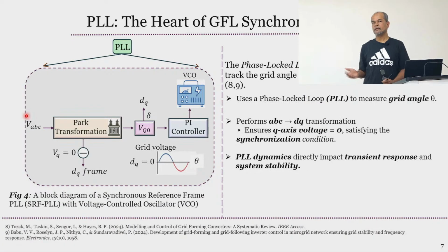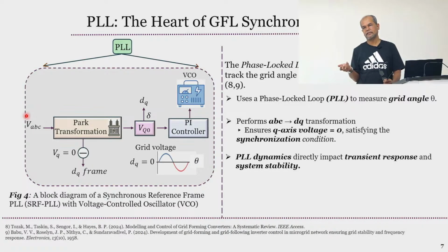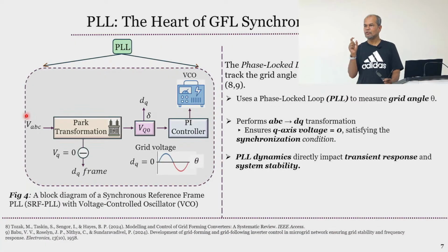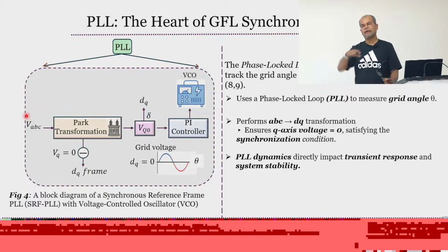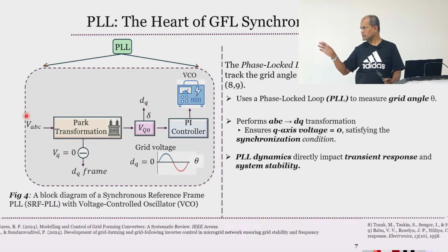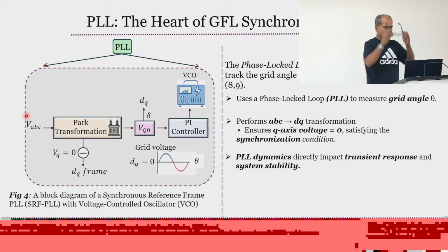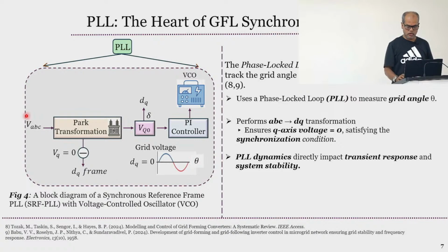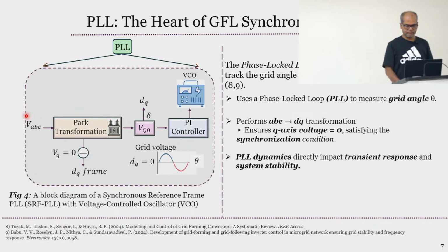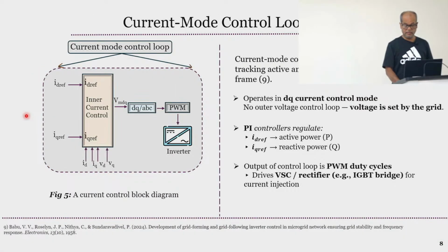There are many PLLs available in the literature, but the very simple one does have problems when you have distorted voltage. If you have a pure sine wave, no problem. But if you have distorted voltage, there are many different types of PLL, yet the PLL still has problems. In that case, as I said, it might affect the transient and system stability.